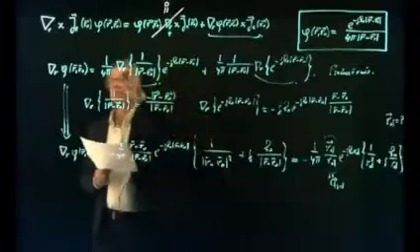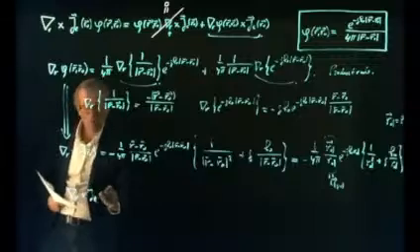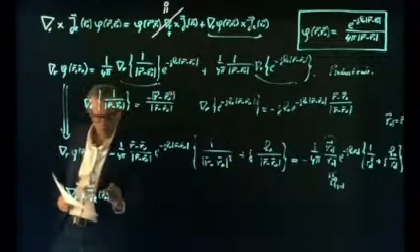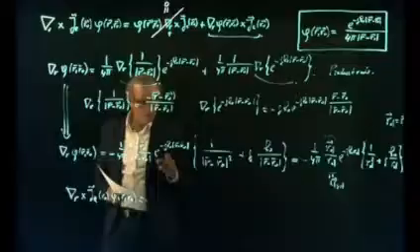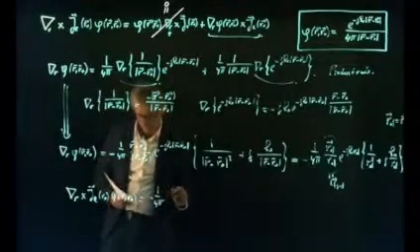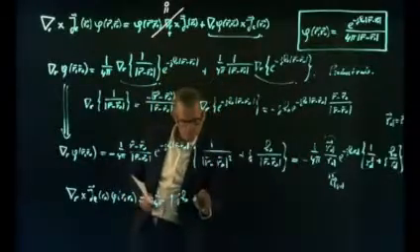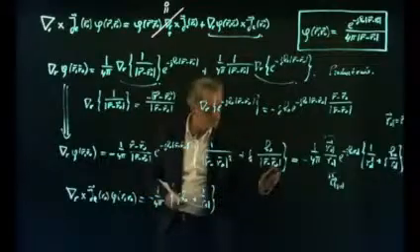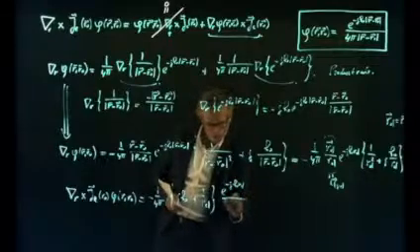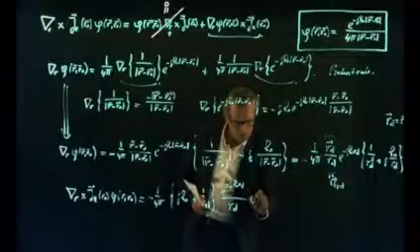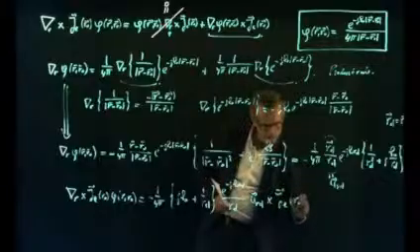Well, that means that this term here, where we were looking for the nabla of phi times the current distribution, is apparently equal to minus 1 over 4 pi, j k naught plus 1 over rd, times the exponential of minus j k naught rd, divided by rd, times the unit vector in the rd direction, outer product with the current distribution.